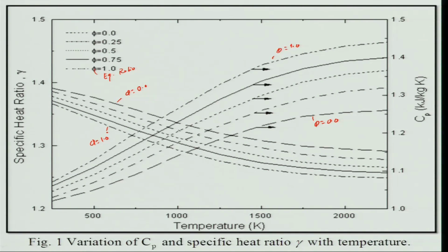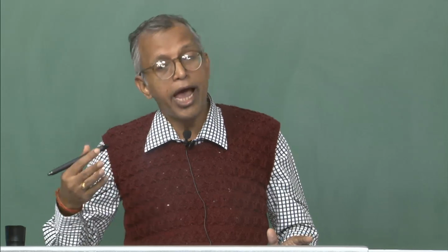Why? For the air intake there is a change in temperature, so I will have to calculate along the air intake how it varies. Similarly, in the compressor or combustion chamber it will be a very difficult job to do by hand calculation, but in a computer program I can, because Cp is a function of temperature, we can get coefficients, and it is also a function of species. It is dependent on species. For methane, for oxygen, for others, you will have to calculate an average Cp. So, it is quite cumbersome.